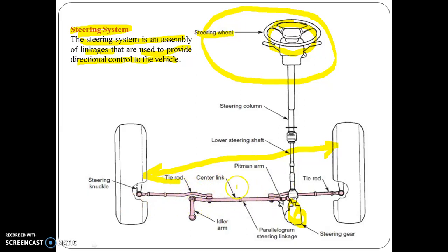Generally, all vehicles use front wheel steering, whether or not they drive is the front wheels, and irrespective of engine position. The steering system, in connection with the suspension system, greatly affects the directional stability at higher speeds, particularly for rear wheel driven vehicles.